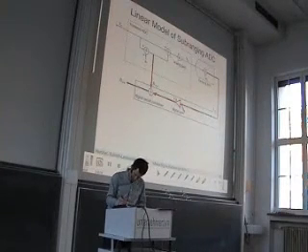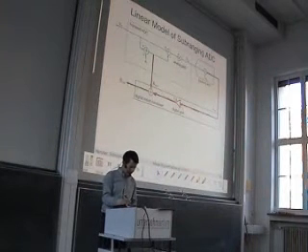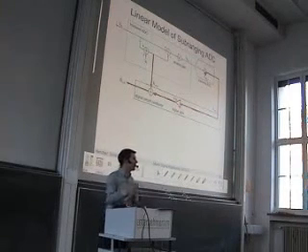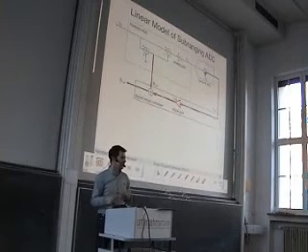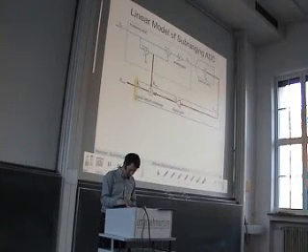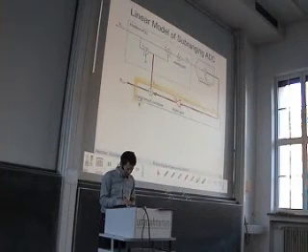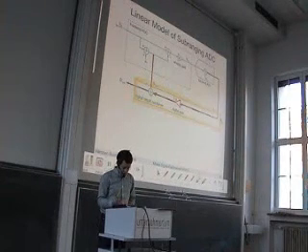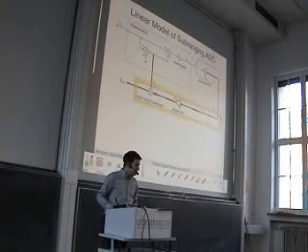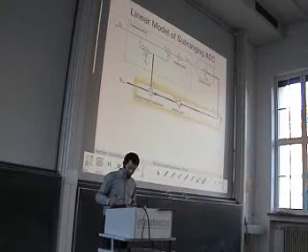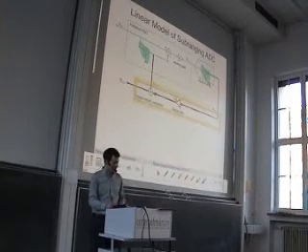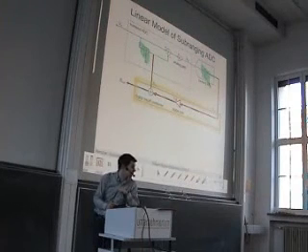Okay. So our subranging ADC is the first stage, which is a coarse ADC. The backend ADC, which is also a coarse ADC but works on the quantization error. And we have here a digital circuit that takes the bits from the first stage and the bits from the second stage and combines them in order to get the overall result. If we insert again our linear model for the ADC, for the quantizers, which means that we use this model and that we use this model, then we can compute the output signal.